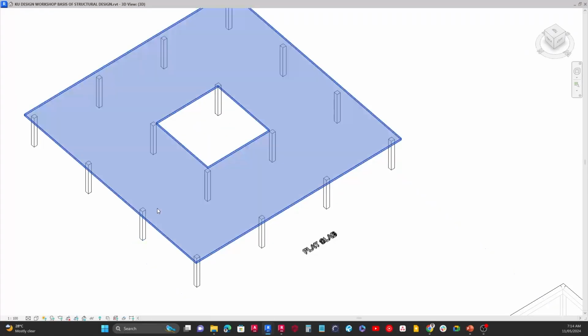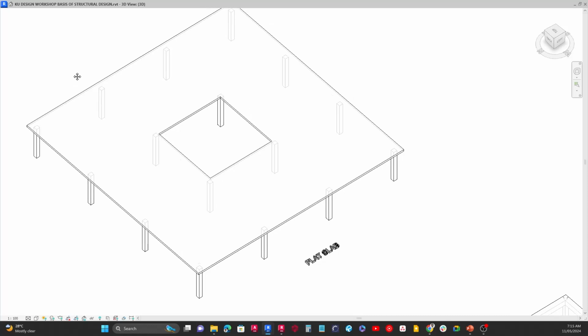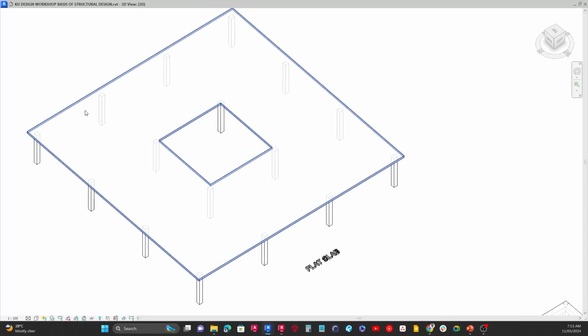Okay, it goes directly from the slab to the column, so there is an absence of beams in those stations. You may see some of these systems, for instance, in large floor areas such as banks or auditoriums, when we don't want to have obstructions on the ceilings, especially when you are doing services such as piping. You don't want to make so many bends, right? So that's why we decided to use flat slabs.